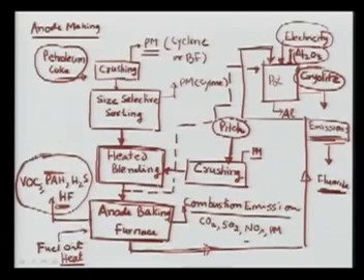So some of the technologies are avoiding the anode baking itself. The argument is that in the pot the temperature is high, so that the high temperature itself will be enough to make that paste solid, and that technology where they use the paste but not pre-baked anode is called Soderberg technology.